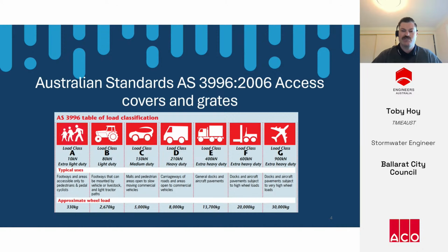When designing drainage, we have to consider the land use where the lid or grate will sit. Different lids will normally be used for vehicle and pedestrian traffic zones. Grates in general should be installed perpendicular to traffic, for example in roadways, so that cyclists don't fall into them. Heel-safe grates is a common consideration for pedestrian zones.